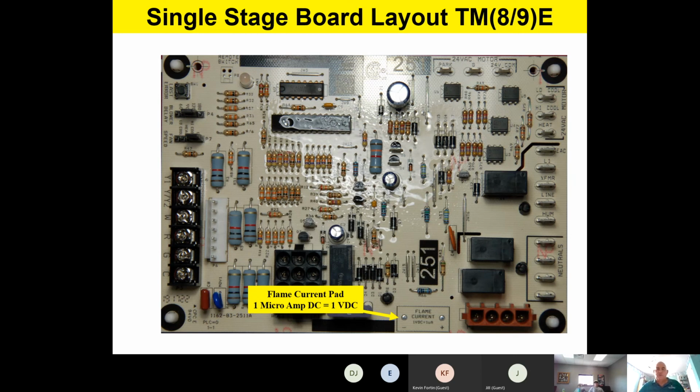So let me say that one more time. Typical flame current with normal running operation is about 3.5 to 4. At 1.5 flame current, you start generating a yellow flash code that says, hey, I'm starting to get low. But at 0.1 flame current, it locks the furnace out.